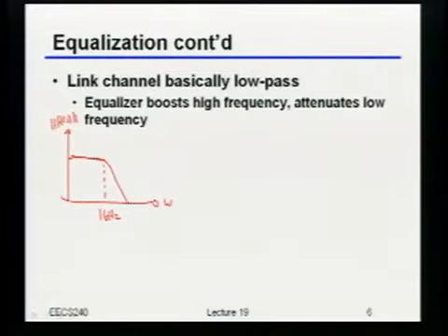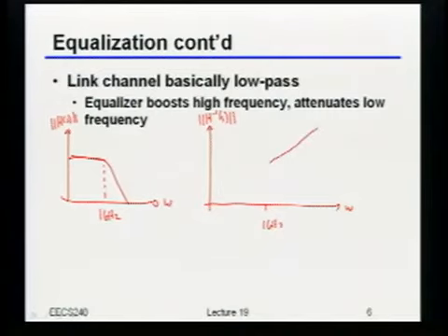So if I wanted to build an equalizer for this particular channel here, what would the magnitude response of that equalizer look like? A 0 at 1 gigahertz. Okay, it'll be a 0 at 1 gigahertz, so there'll be something that'll be doing this. How about the DC gain? By the way, let's just pretend that's 1 right there. Yeah, same. It's just 1, right?